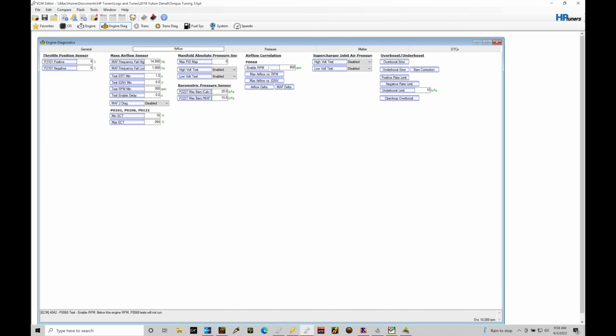So we're going to be opening up the throttle plate. It's then going to take a look at the throttle movement, the actual pressure from the MAP sensor, and the actual airflow amount from the mass airflow sensor. If we're exceeding what the throttle plate versus flow or pressure relationship is supposed to be, it can go into a failsafe mode where it shuts the throttle down. The car goes into what's called reduced engine power and it throws a P0068.